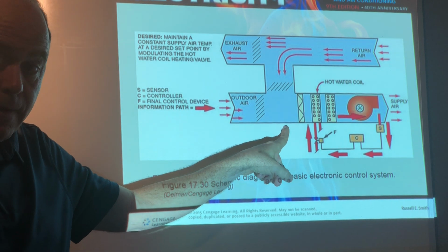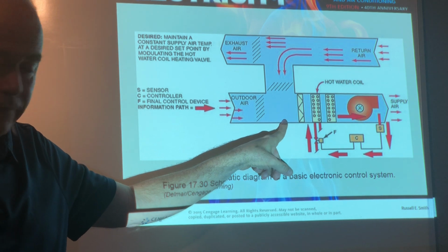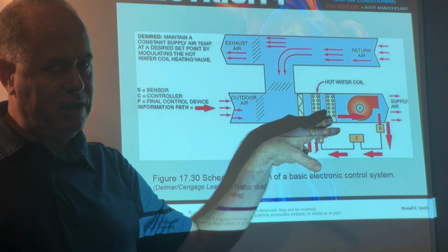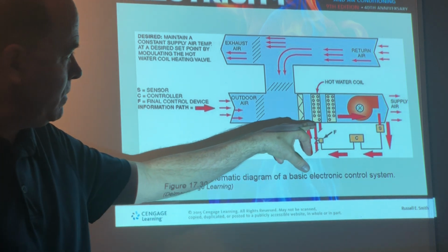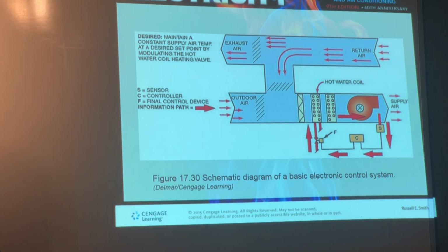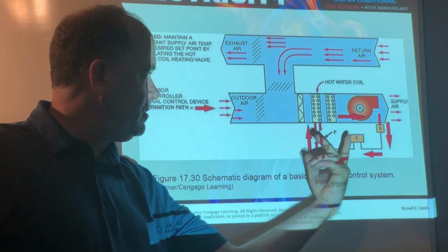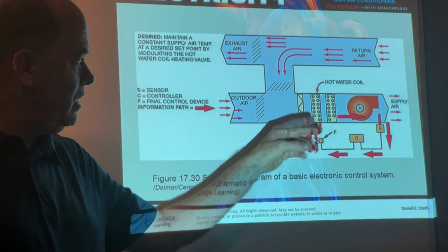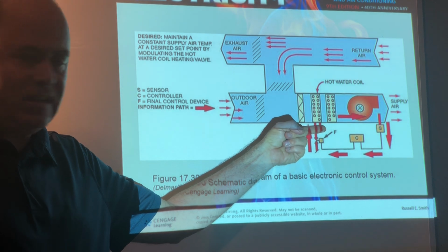This is called mixed air, right before the air filter. And then we go through, this is by far more common than your double duct systems nowadays, this system here. The hot water coil, the chilled water coil. I prefer it when they're flipped, where the chilled water coil is here, because with the chilled water coil, you're always having a condensate pan.